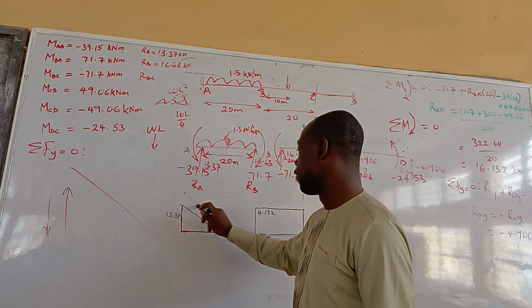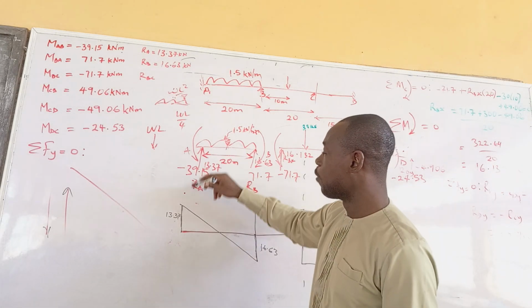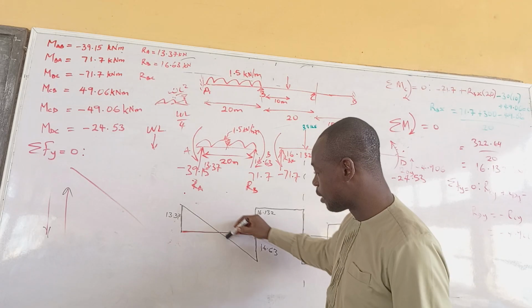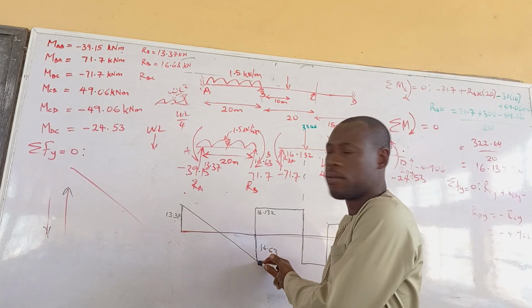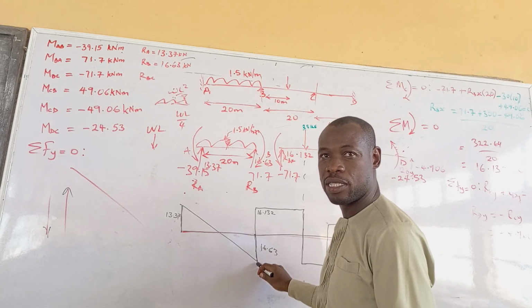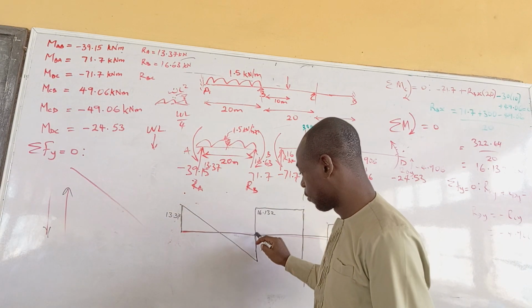However, we're supposed to be moving in this direction till we have a point load. Because this is a uniform distributed load, it's already pushing it downward. So that's why it is slanting to this particular point. Though we don't know where it will end, because we know at this place is 60.63, we know that definitely that's where it's going to terminate. So we draw that one, we finish for this one here.